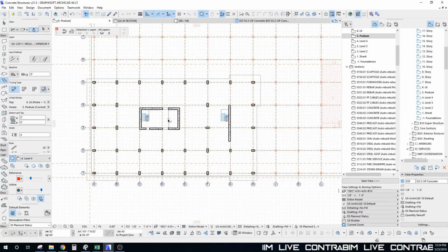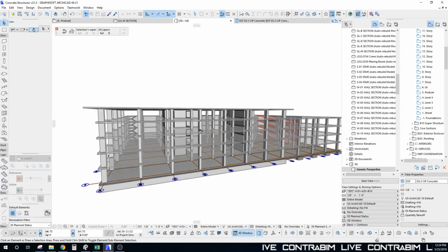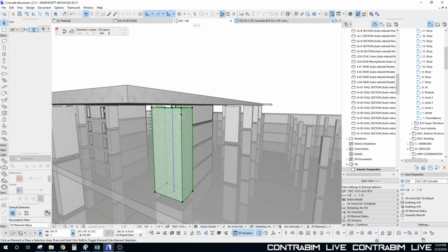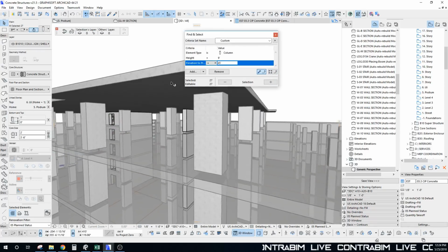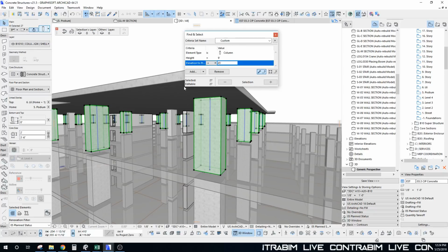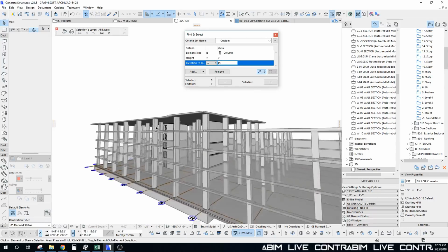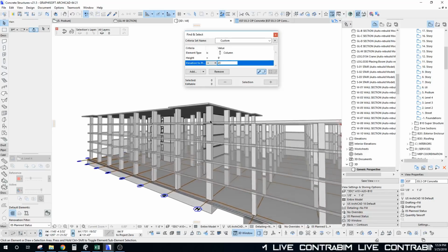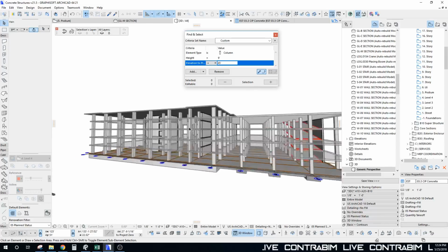And I might have overlapping slabs here. I might have already pasted one up. I think maybe. But let's see. So there we go. We're starting to climb, but we need to go in and find all of these columns and make the adjustment, because now that we have an 8-inch slab, we need to change our top constraint to -8 inches. So there we go. And at this point, we could probably start thinking about shrinking down our column sizes as we go. But we can also play with that at the very end after we've modeled this whole thing.